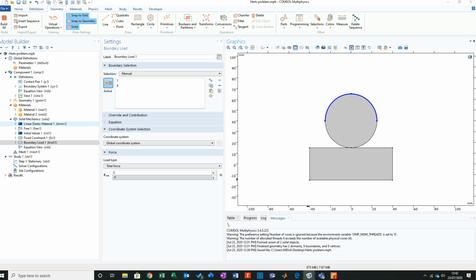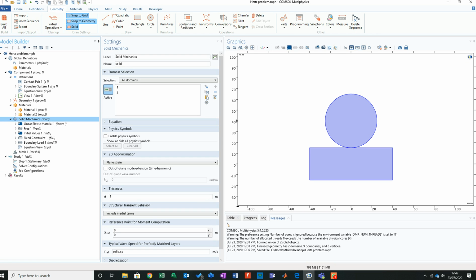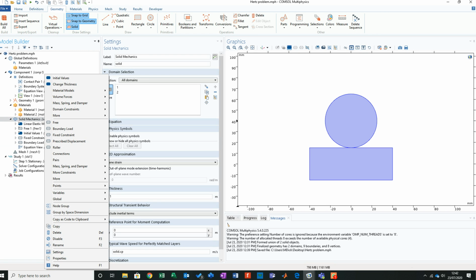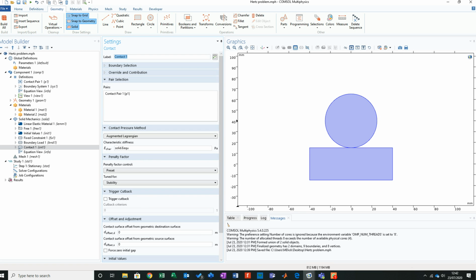Right. Finally, the last thing that we've not added is anything to tell it that it's actually to take into consideration these contacts. So I'm going to right click, then go to pairs, and let's go. Oh, where are we? Oh, contact. So we go onto the contact pair, and I want that to be seen first, so I'm going to put that up there. You see there, contact pairs are in there, so it already knows what it's doing. It's going to be picking that one up.